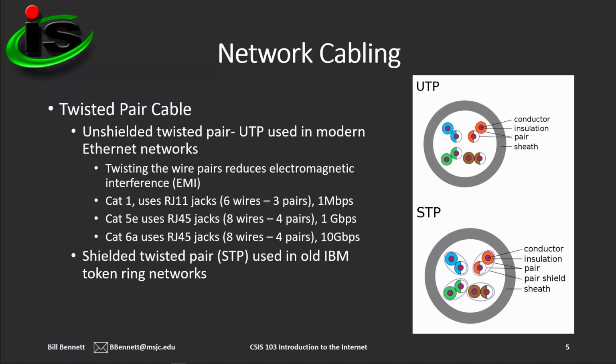A wire that carries an electrical current generates an electromagnetic field around itself. The electromagnetic field can induce a small flow of electricity in nearby objects, including other wires. This induced flow of unwanted electricity is called electromagnetic interference, or EMI. In twisted pair wiring, the wires are twisted because wrapping the two wires around each other reduces the amount of electrical interference that each wire in the pair might pick up from other nearby current-carrying wires.